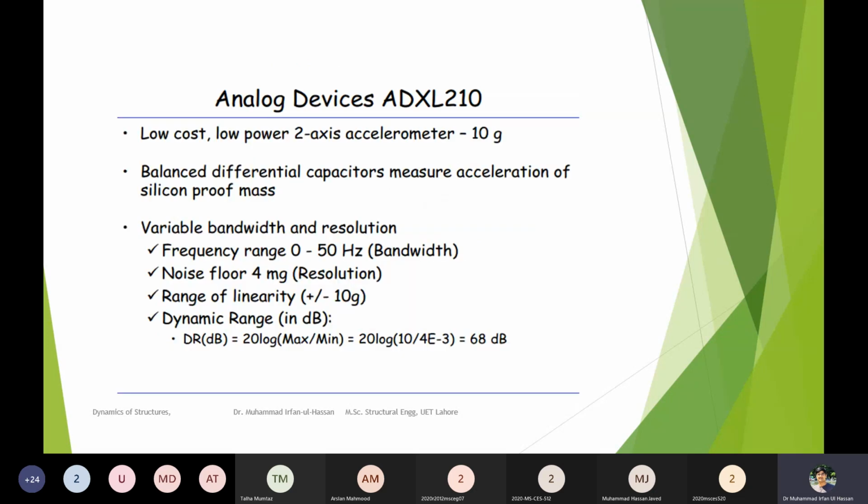Of course, sensitive instruments are costly, especially for civil engineering structures, where the time period is small, and for smaller values we have to see what is critical. The sensitivity and precision of the equipment required is high. For any vibration measuring instrument, we also have in the department laboratory, the values are given: what is the frequency range, the range of linearity, the dynamic range.